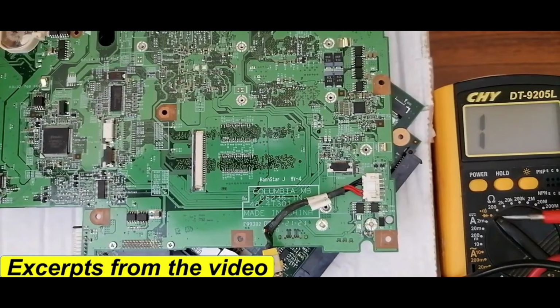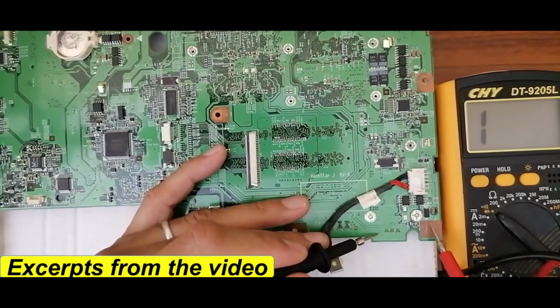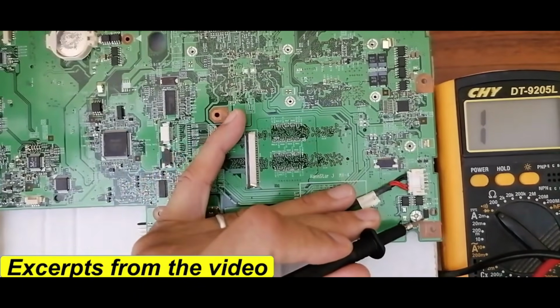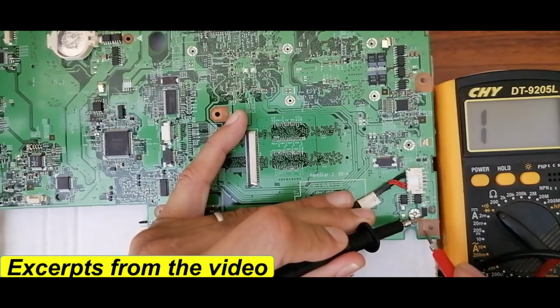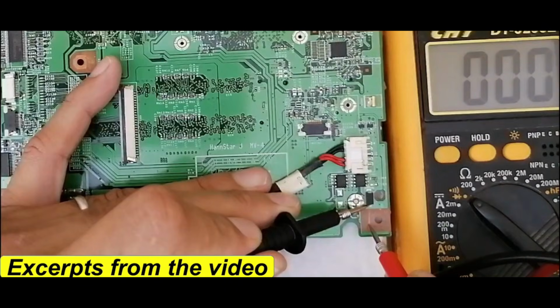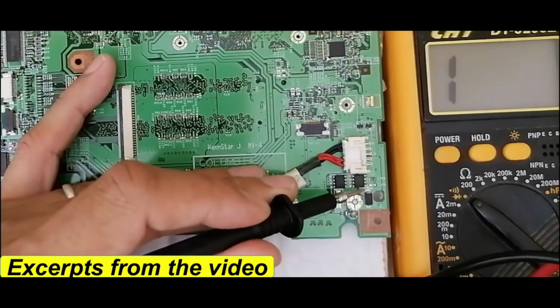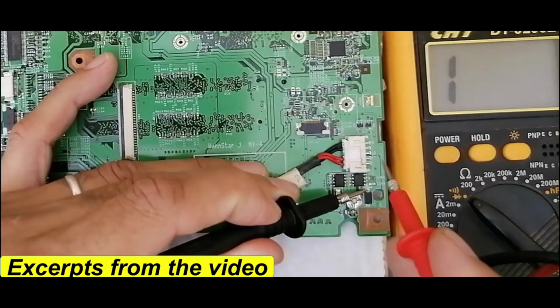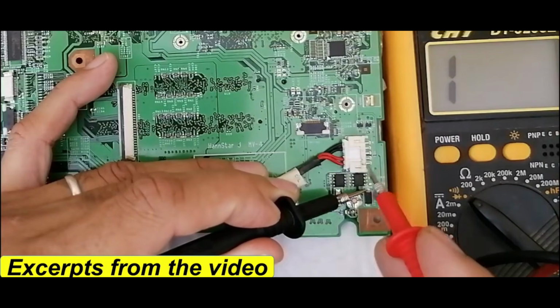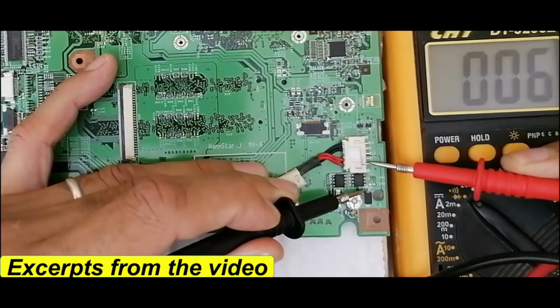We're going to select the continuity option in the multimeter because we're going to check continuity. As I told you, this is the anode, so the anode should be connected to the ground. As you can see in the multimeter, we have a 0 reading and a buzzer, which means the anode is connected to the ground. But the cathode should be connected to the main 90 volt power rail, to this red connector. So let's check.